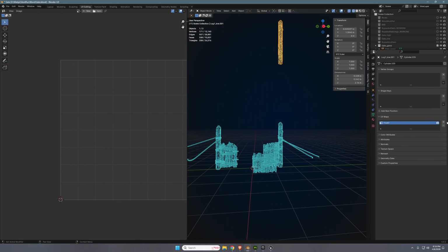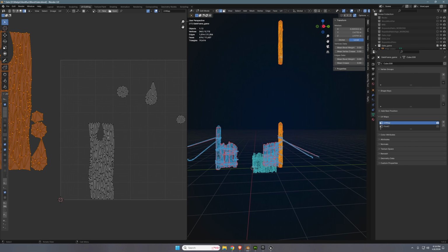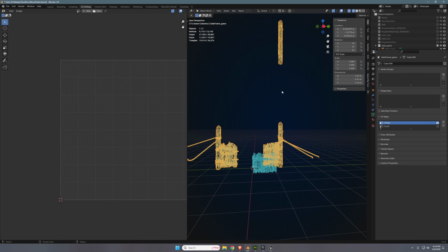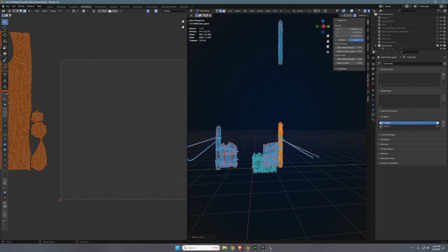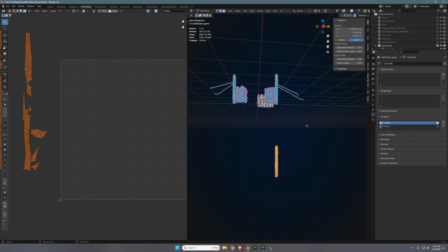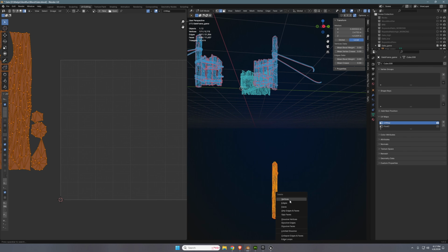So what we want to do is select our log here and then just press the little plus button. This will give it two UV channels, and once we join the meshes together now, it will work perfectly because they'll have their UV channels synced. And the only thing left to do now is select both of these meshes and just move the upper mesh to the same position as the lower mesh was, and then just delete the old mesh.